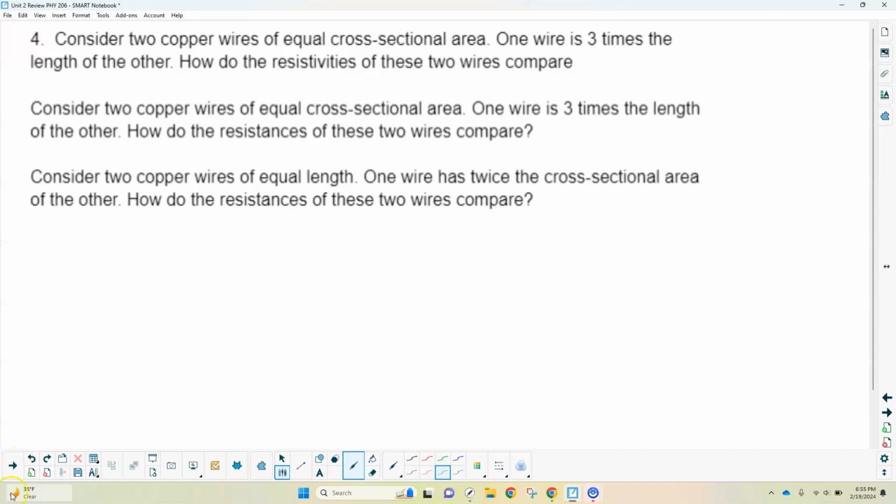So that's the first 3 questions. The fourth one, we're talking about resistors. In resistors, there was a resistance equation based on physical properties. So it's R equals rho L over A. Just to talk through these different ideas, rho is called the resistivity of the material. It's basically just describing how good of a conductor it is. So the better the conductor, the bigger this number is. I'm sorry, the more of an insulator it is, the bigger this number is and the bigger resistance. I misspoke.